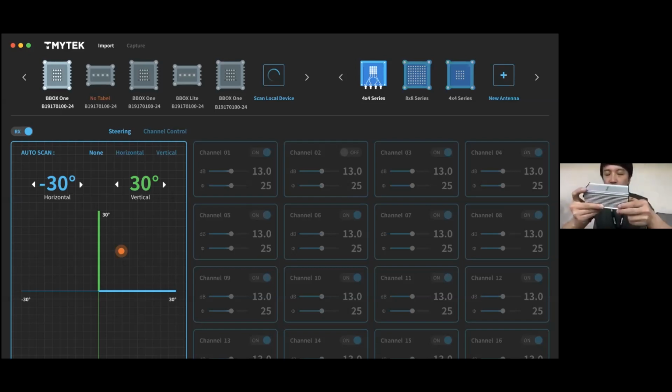From our specification, we documented it as supported from 25 to 31 gigahertz. That's super wideband. All the devices here, the power amplifier, low noise amplifier, switches and phase shifter, they all support that wideband. So we claim 25 to 31 gigahertz for this one. But your observation is exactly and very precise. Now, the bandwidth limitation was here.